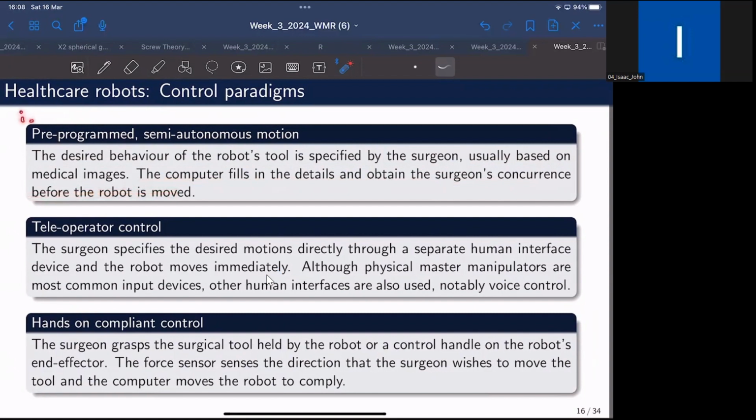Right. So, probably the surgeon could be defining the movement in a discrete fashion, and the computer can basically interpolate what is being described by the surgeon. Once it plans this path, the robot will ask the concurrence of the surgeon whether it should execute this task which it has planned or not. Once it obtains the surgeon's concurrence, it will execute the task. So every time it will ask for surgeon concurrence. And as a result, it's not fully autonomous; it's semi-autonomous.